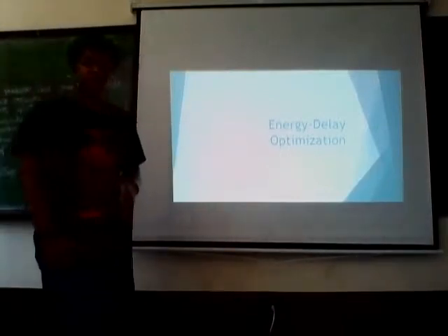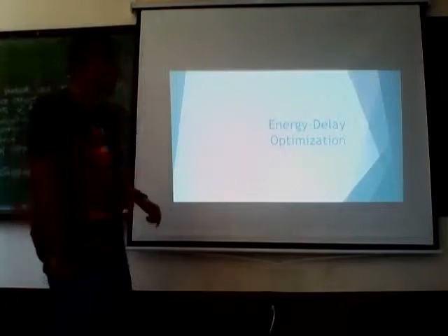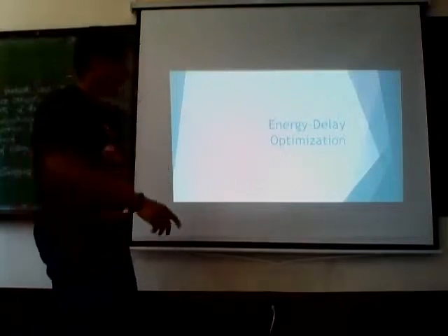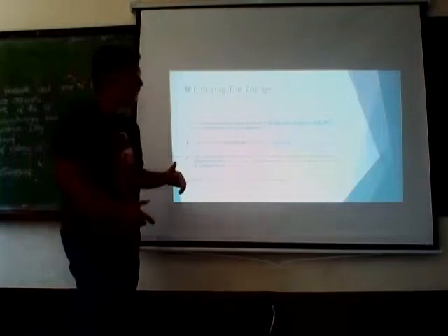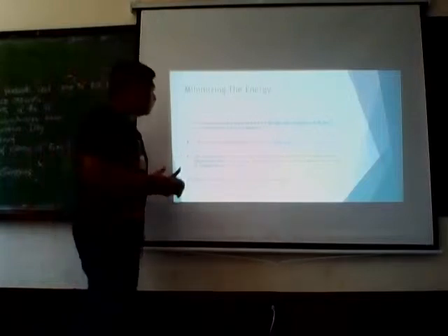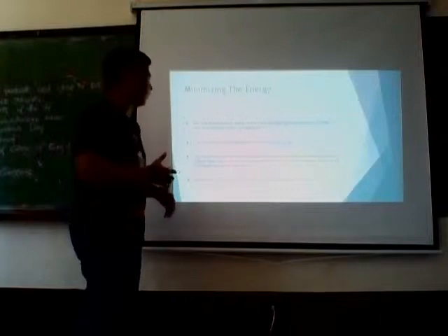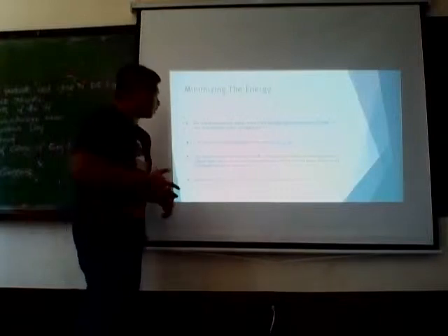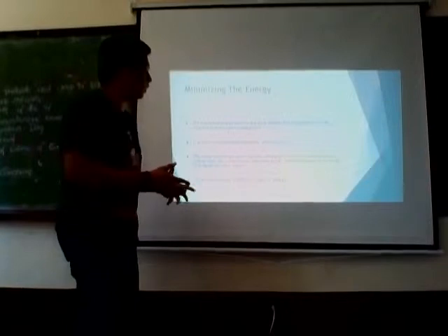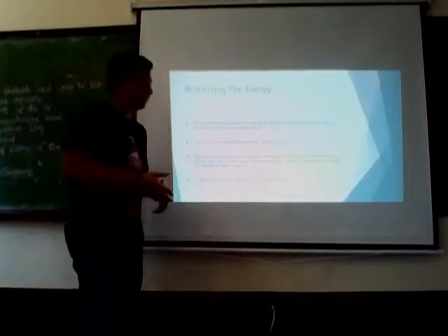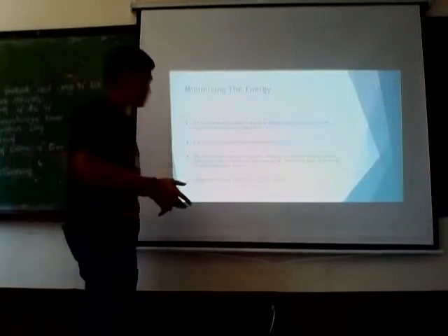Chapter 5, 5.4 Energy Delay Optimization. Minimizing the energy. The minimum energy point is the least energy that an operation will consume if delay were unimportant. It occurs in sub-threshold operation, where VDD is less than the threshold voltage.